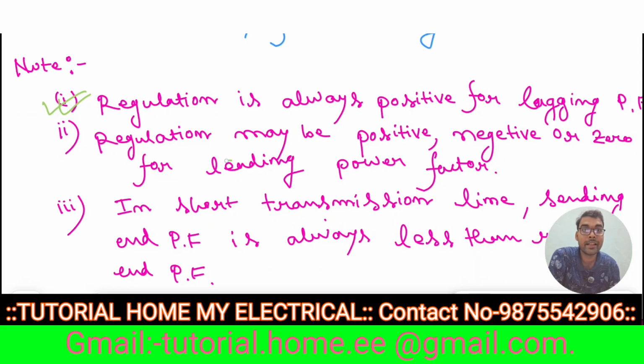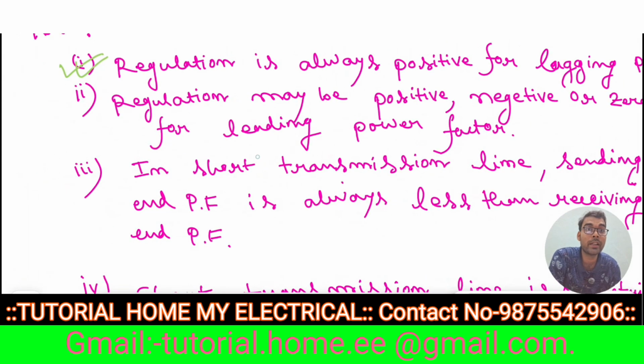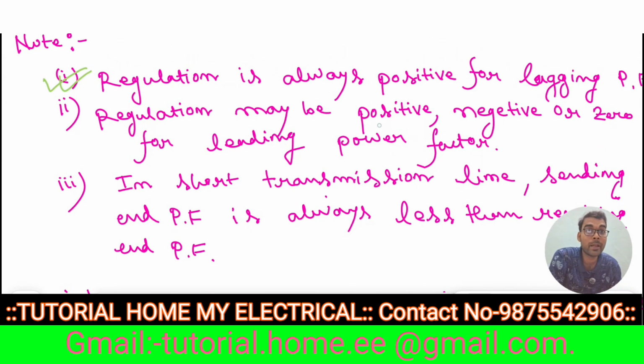And next, regulation may be positive, negative or zero for leading power factor. For lagging power factor, regulation is always positive, but for leading power factor, regulation may be positive, negative or zero.